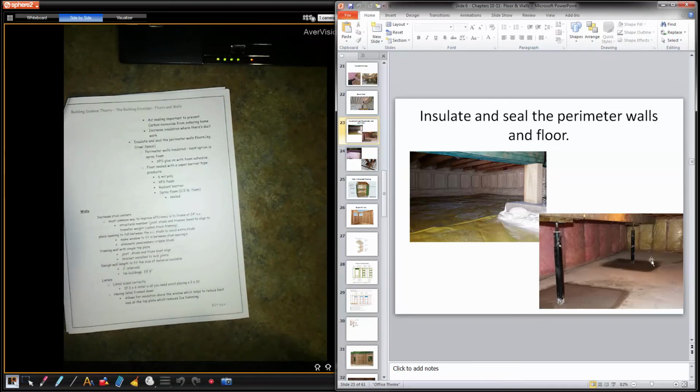So cut out the slab, which is probably only 4 inches thick. They probably dug down below the slab, maybe 12 inches or more, depending on whatever the engineer required. Then poured that footing and slab at the same time, and put the post on, and away you go. Foundation walls are just fiberglass with 6 mil poly. So pretty common, but not really the best products.